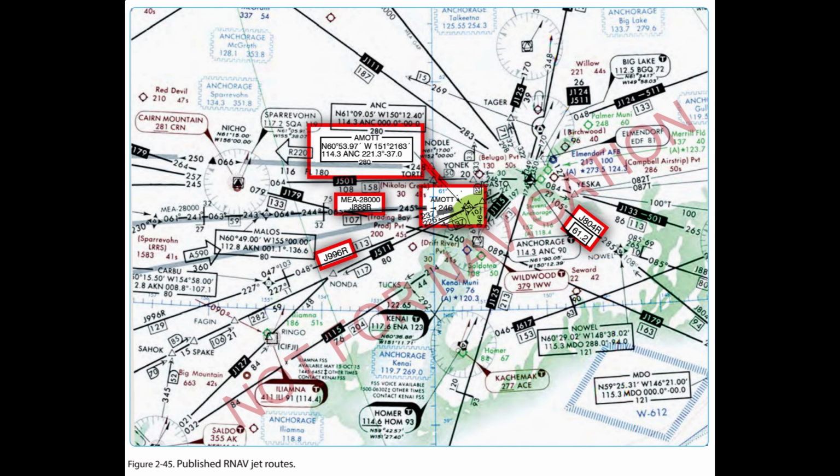Navigation is the pilot's responsibility unless ATC assistance is requested. 9. Plan the route of flight so as to avoid prohibited and restricted airspace by 3 nm unless permission has been obtained to operate in that airspace and the appropriate ATC facilities are advised.